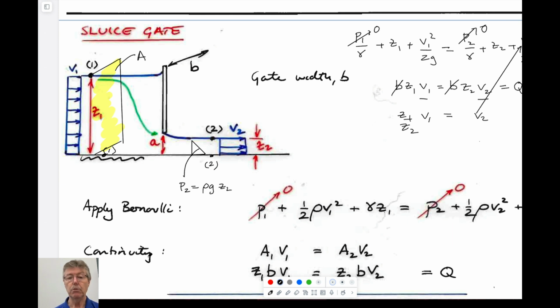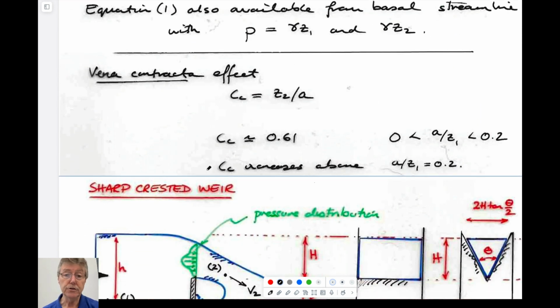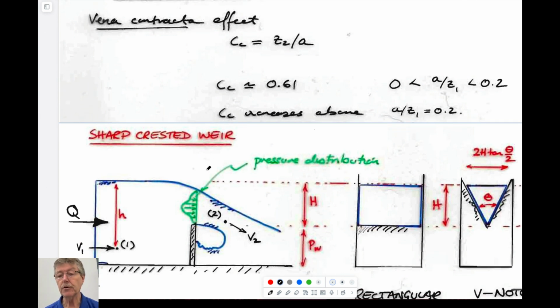Just from what we've talked about with fluid statics, and Bernoulli, fluids going across curves, into curves. When you go into a curve, this becomes flatter and the pressure increases, just as you feel the pressure increase in your seat as you go through a dip in a car. And if you go over the lip of a curve, then the pressure in the cup that you have is reduced. That's the same. If it's going horizontally straight, then it's just swimming pool pressure distribution, as you'd expect it to be. And there might be some corrections you could apply.